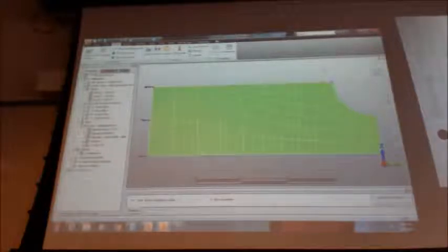So you can see here, these constraints along the top prevent it from translating in the z-axis, and these constraints on the right end just prevent it from translating in the y-axis. And then it seemed to behave more appropriately, more the way I expected it to behave. So I don't know what I'm doing wrong with the frictionless, something we have to learn or figure out about the software.